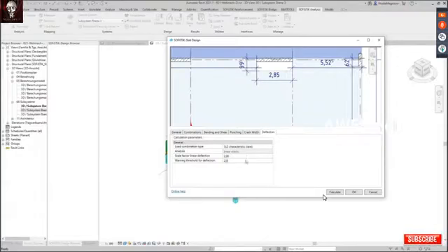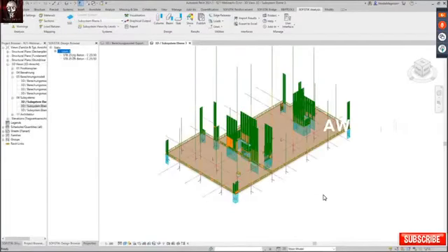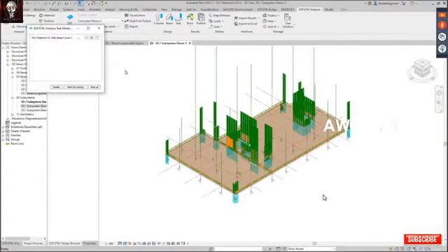In order to compensate that and to give you an estimate, you can define a linear factor to increase the deflection. And you can also generate a warnings result. I will show you what this means afterwards in the report. Once you define all your options, you can calculate your design. So you can start the calculation of the design of your slabs.